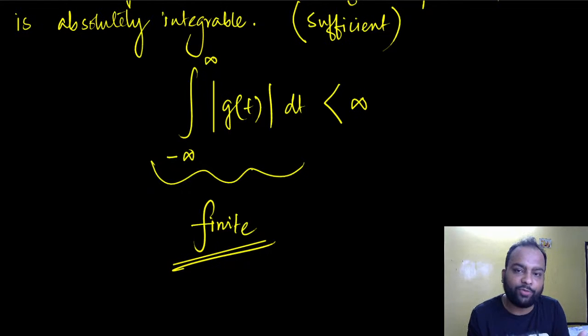And if you have a Fourier transform, then you also have a Laplace transform. But for unstable systems, you don't have a Fourier transform, but you have Laplace transforms. Get the point here? So this is also the condition for existence of a Fourier transform. If you recall, we discussed all these things earlier. So yes, for BIBO stable systems, the impulse response is Fourier transformable. The impulse response is expressible in terms of sinusoids. That's true.